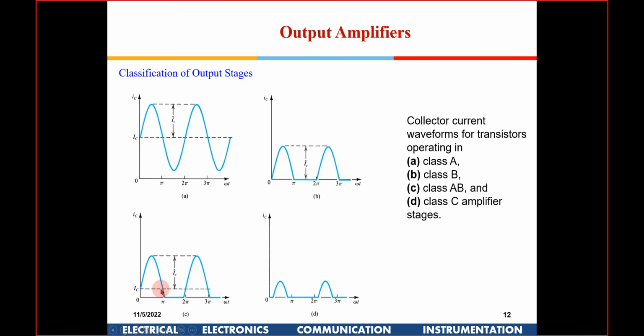That means in this small region here, two transistors will be simultaneously conducting. That is to avoid linearity issues, because when the current is very low here, if you have exactly 180, there could be an issue during the crossover that the signal is not amplified.